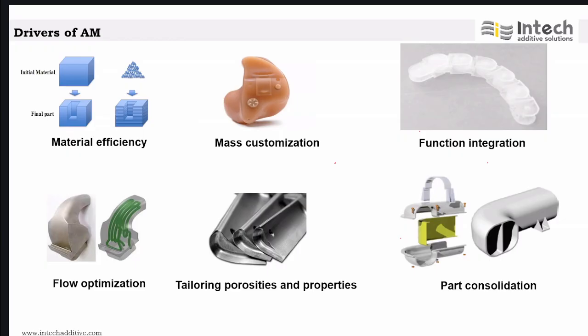And also we can have control over the grain boundaries. So it helps to influence the material strength, ductility, and fatigue resistance. And it finds its applications in graded materials, like where a hard surface is needed for wear and a tough interior for impact absorption, and so on. The last one is about part consolidation. Any doubts here?